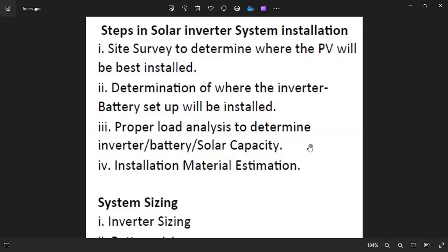So actually the lithium-ion battery doesn't emit any gas, but it's explosive in nature. We should have it at the back of our mind. So we should never install any lithium-ion battery that doesn't have a battery monitoring system. It could explode, you understand?